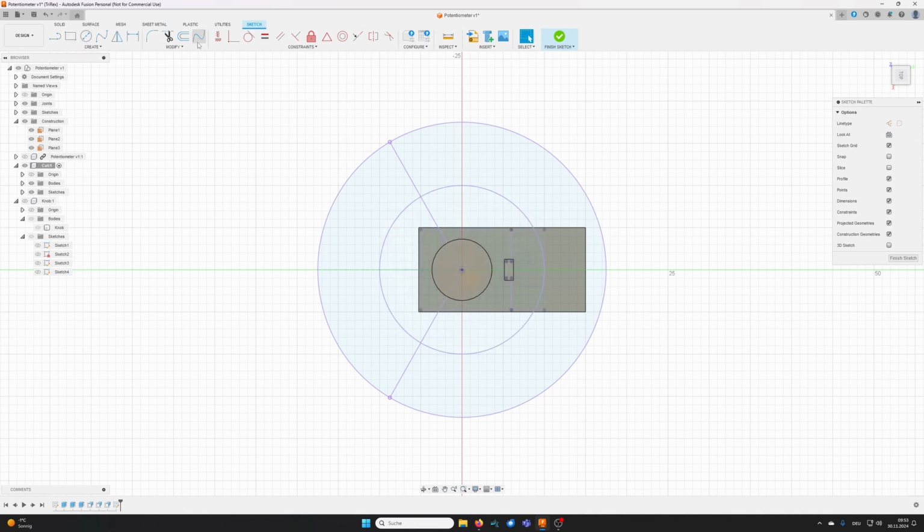And here we'll add an offset line, negative 1.5 millimeters, because the notch has an overall width of 3 millimeters and the offset of 1.5, then the middle axis of my notch will be on this line and will collide with my top component over here. Let's do this as well with the other line, 1.5.